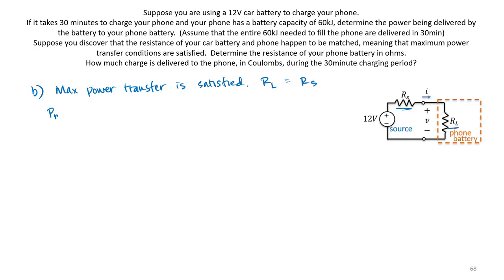And that also means that the power we're transferring is equal to our source voltage Vs over 4 RT, where again, RT is the Thevenin equivalent of our source circuit, or Thevenin resistance of our source circuit.